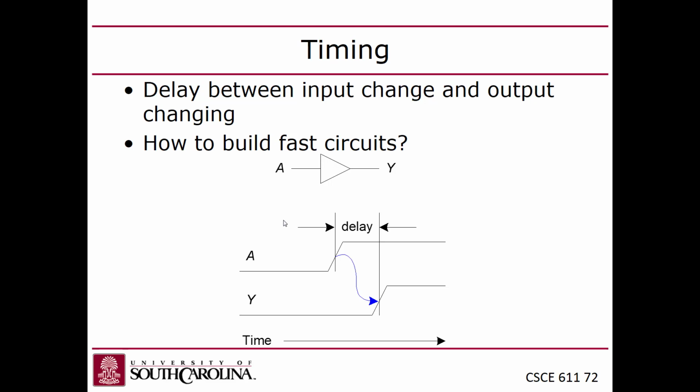Do all gates have the same delay? No, it depends on the gate. Also, it depends on what the gate is connected to, which is something they don't talk about in this book. But the gate delay can also be determined by how many other gate inputs it's driving, the capacitive load of its output. But in this class, you only have to worry about the fact that there's this propagation delay.